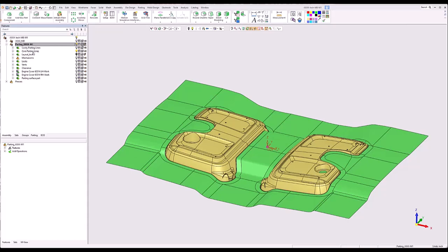And you have lifter pockets that may go into the core side. Inserts could be in core and cavity sides, but you can do all these features or modeling inside these skins and then use the skins to cut the core and the cavity block. If you put those modeling features into the core and cavity block, what it does is causes regeneration to take longer, particularly if you're doing stitches and you have multiple stitches in a core and cavity block. It really becomes noticeable when you edit, move a screw, remove a screw. It takes longer to regenerate through those.